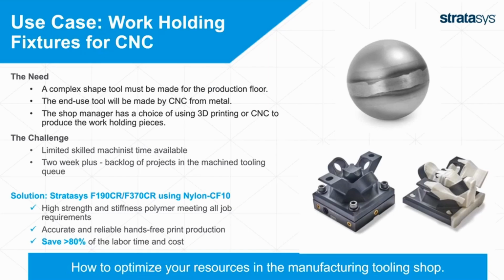You can print what you want, not what you are limited by other processes. So the soluble support helped enable this application. And the biggest advantage for 3D printing is more complex parts. And so you're able to sometimes combine two tools into one, and accomplish more with less. So it's an easy iterative process with low learning curve. So here they were able to take what might have been previously CNC'd for a work holding fixture, 3D print it, save time and money. So a great application. And it was enabled by having the carbon fiber filled nylon CF10 material.